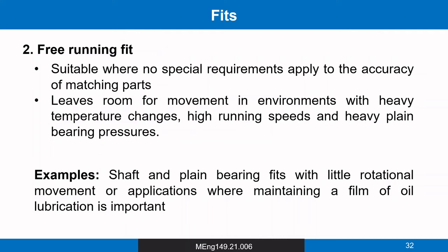The second is the free running fit. This is suitable where no special requirements apply to the accuracy of matching parts. This leaves room for movement in environments with heavy temperature changes, high running speeds, and heavy plain bearing pressure. Like the loose running fit, this allows movement between the parts, but it also allows higher running speeds.